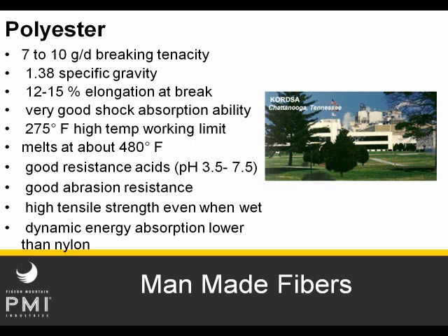Things to be particularly careful of with polyester rope are its lower dynamic energy absorption and the fact that it's more slippery to rappel, lower, or belay on than with nylon.